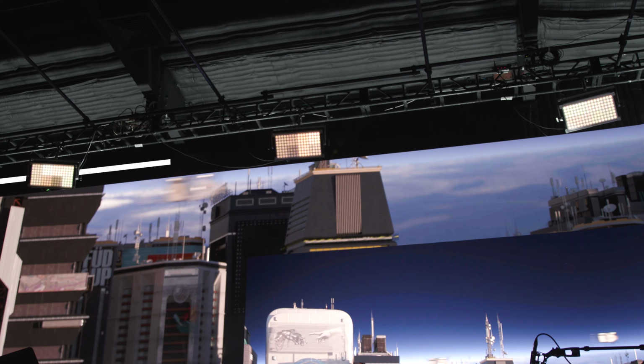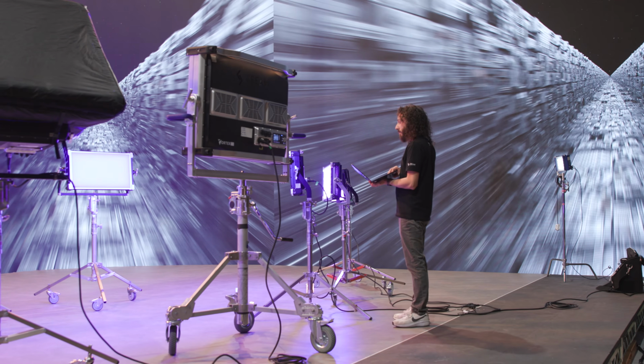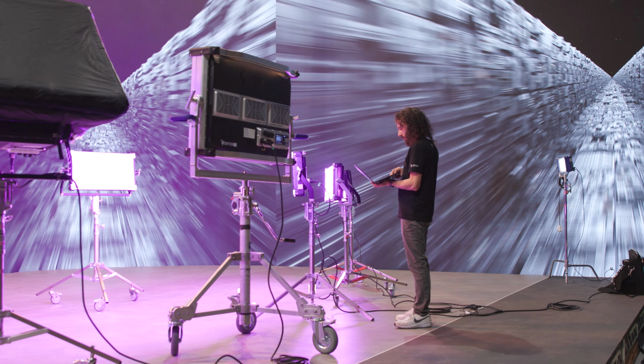Here at E11 Studios in Hollywood, we are networked to our Vortexes on top of the LED wall with streaming ACN via Ethernet. I'm also going to take advantage of the DMX forwarding feature that is built into all Vortex fixtures. DMX forwarding allows you to forward the chosen streaming ACN universe out from the DMX port, no node required.